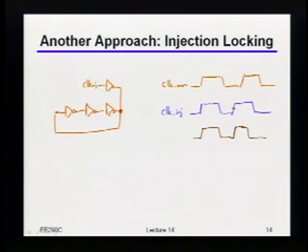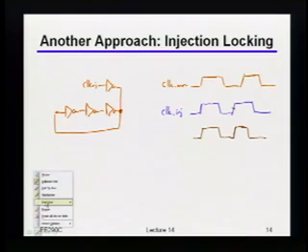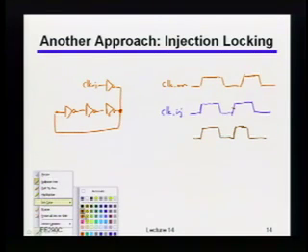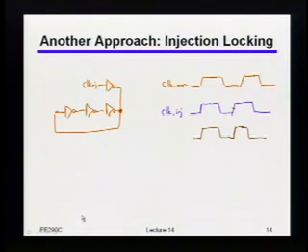Turns out that the amount that it's going to be skewed by is directly related to the frequency difference between the two oscillators. Okay? And the picture that hopefully will give you an idea of why that's the case is, imagine that I made this injection clock really fast, right? So again, I'll line up this first edge, but I'll make the next one much earlier, right? If I make that edge much, much earlier, that implies I'm pushing that nominal clock in farther.